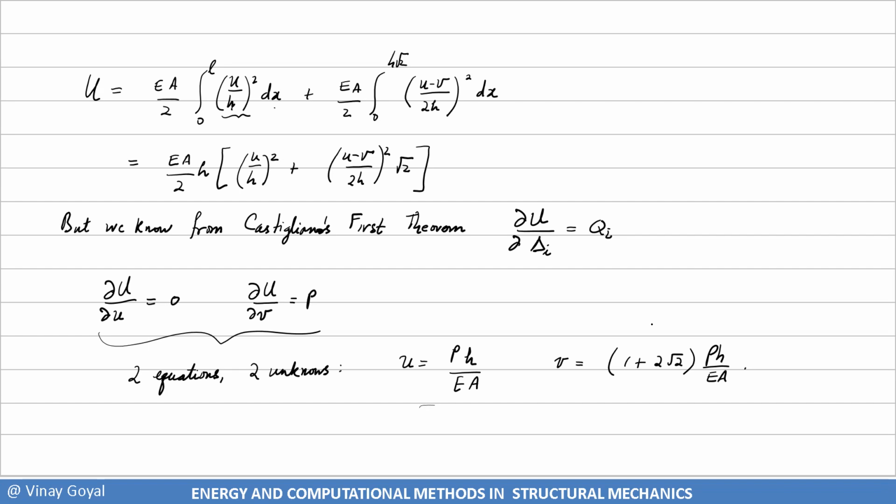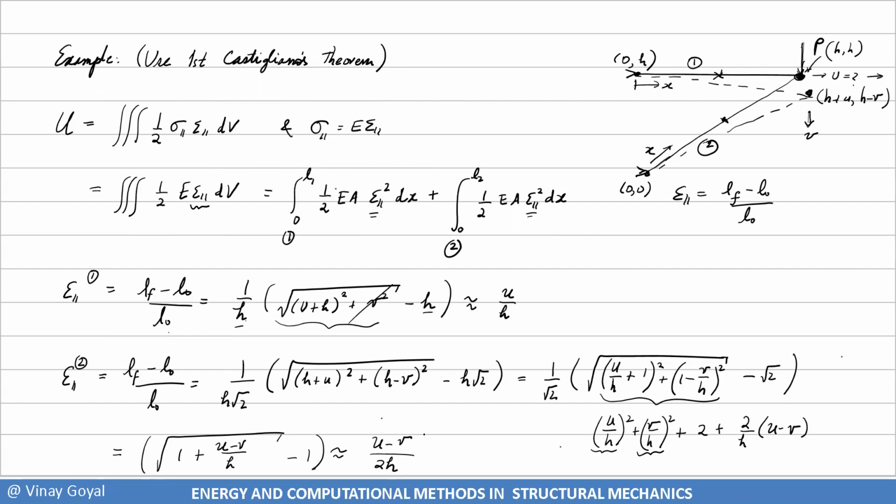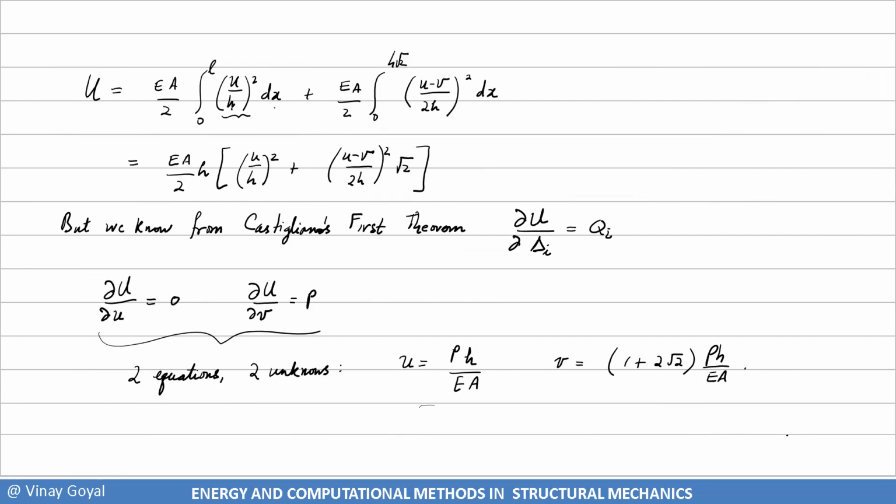And then I showed you a new theorem called the first Castigliano theorem, which shows the convenience of this theorem by showing you I can get the deflections by using this simple formula. In other words, if the strain energy can be written as an expression of discrete deflections applied, and I were to take these derivatives, I can equate that to the load at that particular point where the deflection was applied. And that's going to help you calculate the deflections you're interested in. With that said, I will conclude today's lecture, and I appreciate your attention today.